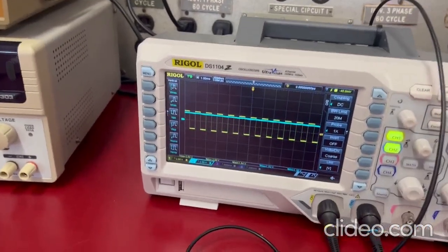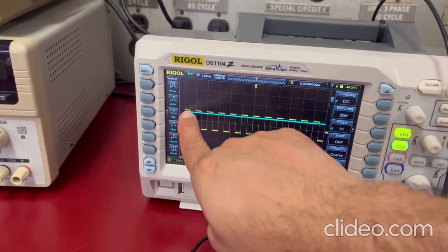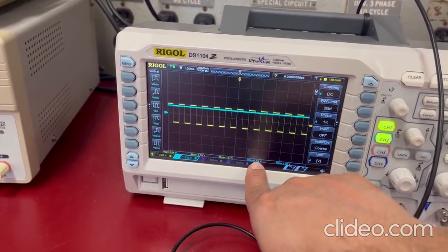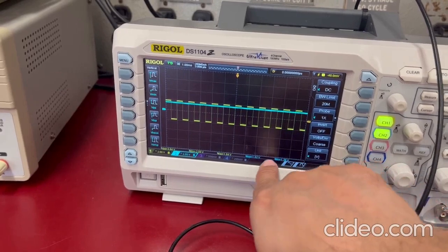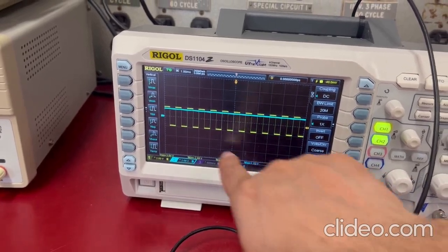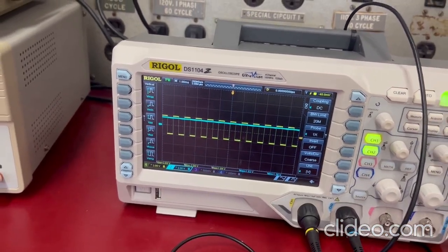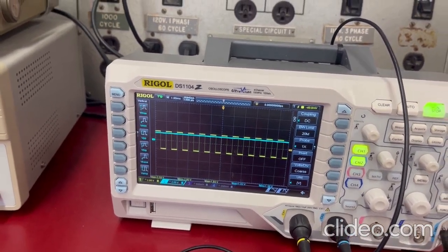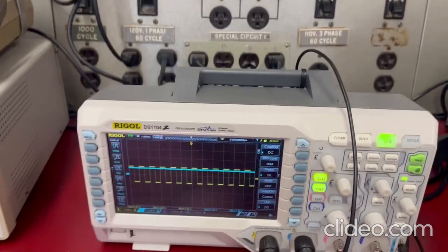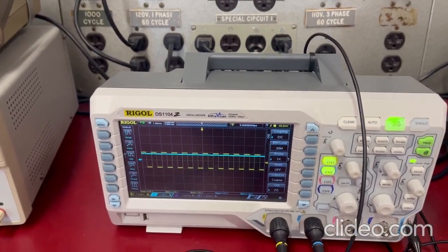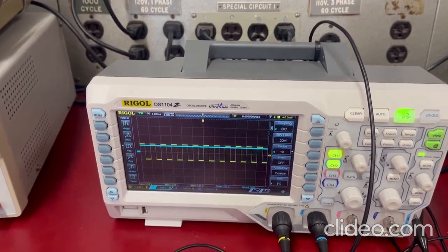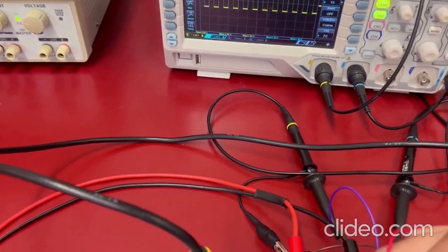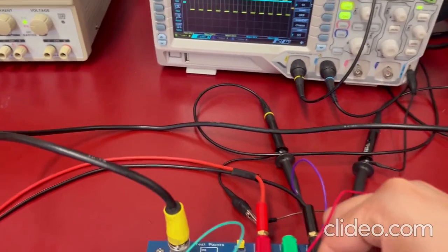You can see my signal is around 2 volts, and you can also check it from the min and max, that it is around 1.5 volts. So there is a little bit of voltage drop. That's because of the diode. It's not exactly VDD, which is 2 volts. It is less than that because of the drop across the diode. This is verified with the handout results.